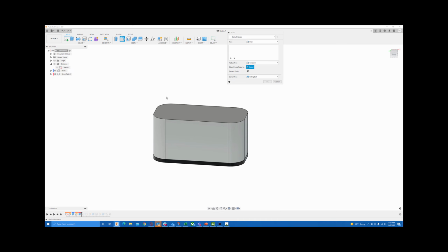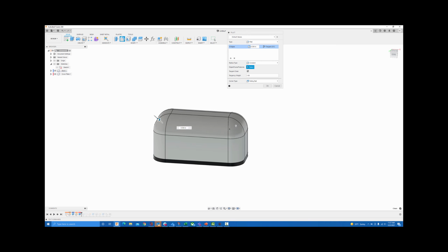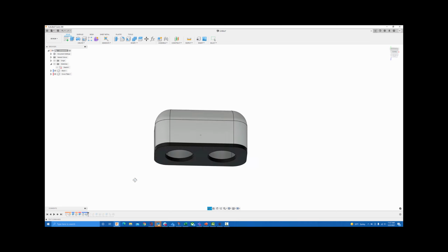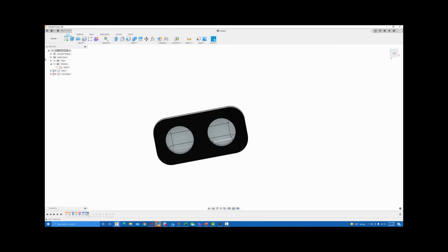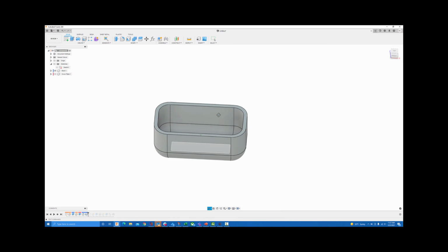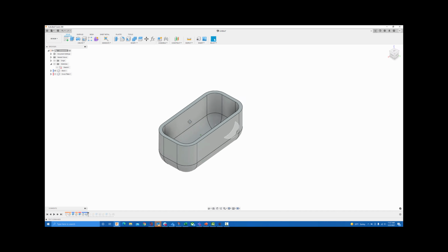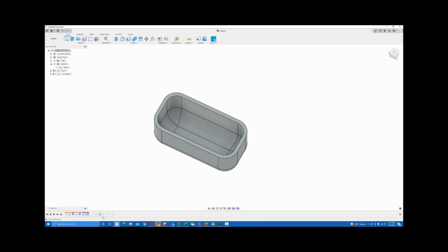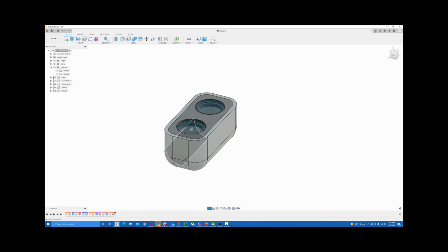And then I'm going to come in and put a fillet here, and we'll drag it to be pretty big, something like that. And then if I roll forward, that is my shell, and you'll notice if I turn off that front cover plate that it has a nice fillet on the inside as well, which if I had added that fillet after the fact, it breaks it like that. So just something to keep in mind, that it does matter how you assemble things, kind of the order in which you go about it.